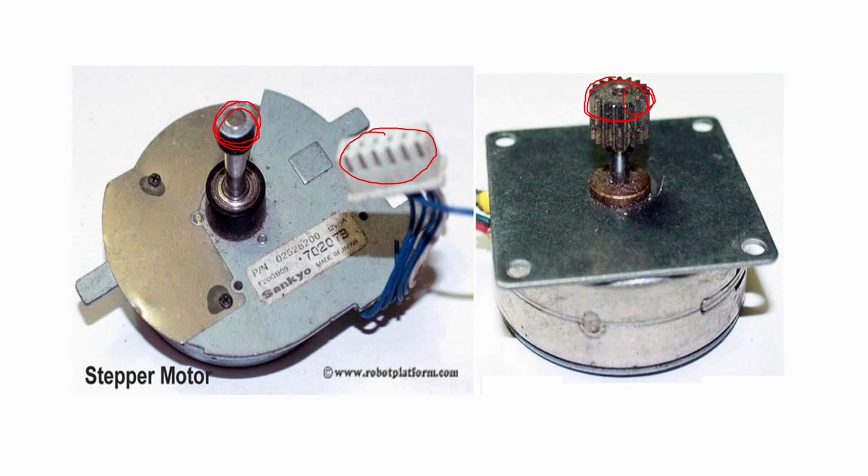Here the stepper motor is a special type of DC motor. It has an incremental motion, so it is an incremental motion machine. It is a permanent magnet or variable reluctance DC motor and has the following characteristics. It can rotate in both directions. It can move in precise angular increments. It can sustain a holding torque at zero speed. It can be controlled with digital circuits. So these are the very important